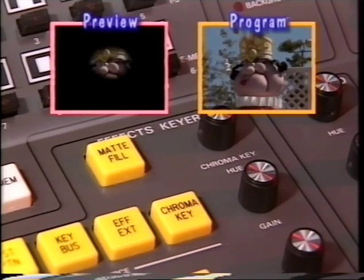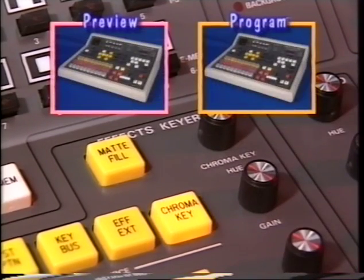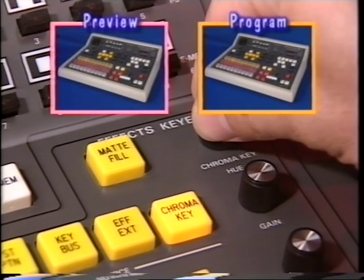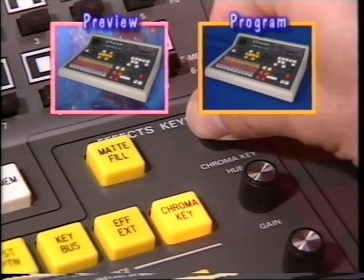Now let's continue by looking at the third and last type of key possible using the Model 110: chroma keys. The chroma key push button on the effects keyer selects the chroma key mode if the chroma keyer is installed in the switcher. Chroma keys differ from luminance keys in that a hole is cut in the chroma key scene on the basis of color, not on the basis of signal brightness. For example, if blue is the chroma key color, the blue areas of the chroma key scene are removed and replaced with video from the program background bus.